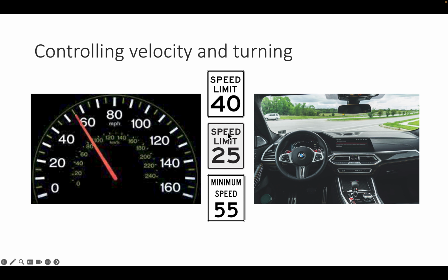In this case, you have to do a right turn. And also here, you will turn more if the error is big and turn less if the error is small. It also depends on the speed you actually drive, but we will not get into this. What I want you to take home from this slide is that the difference between what you should do and what you currently are doing is what we call error, and your behavior should be a function of the magnitude of that error to compensate for it.